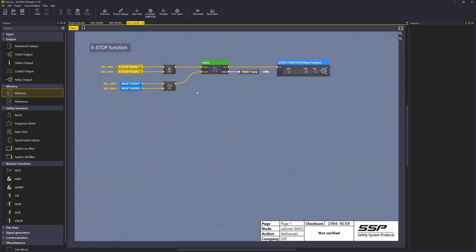One important thing is also, in this case we have only 3 units, so it's no problem to keep an overview about the logic. But there's a sentence which is important to keep in mind if you program wireless systems. Always make the logic where the output switches something off.